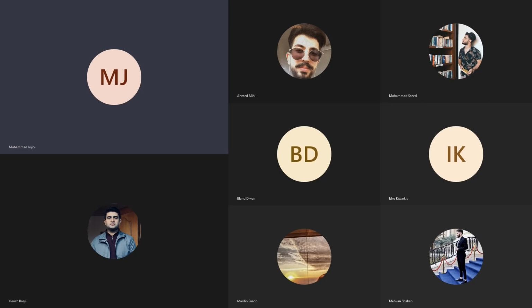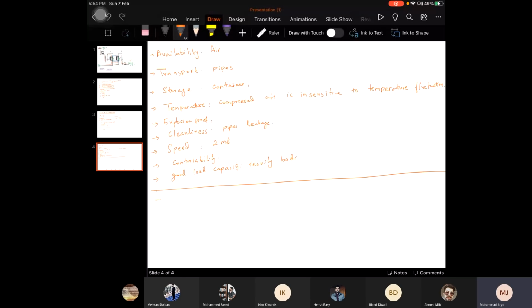All right. The other disadvantage is that compressed air is only economically viable up to a certain expenditure of force. The traditional operating pressure is normally approximately 7 bars. But attaining very high pressure is very difficult, and it can be very expensive to attain large pressures.